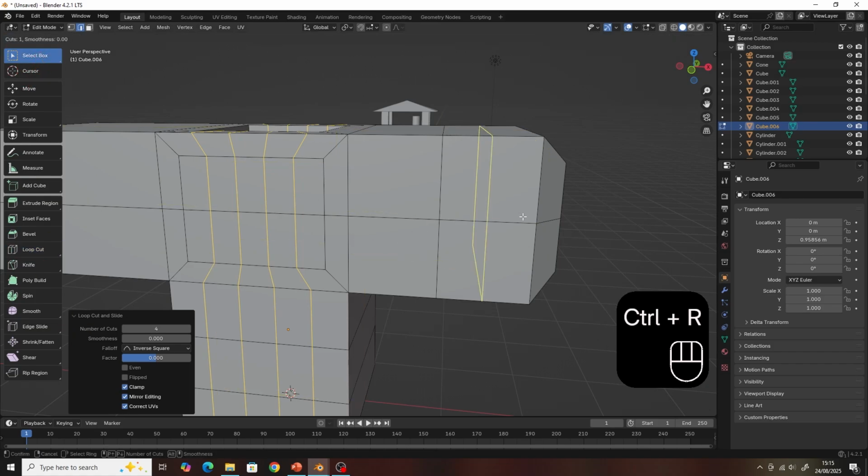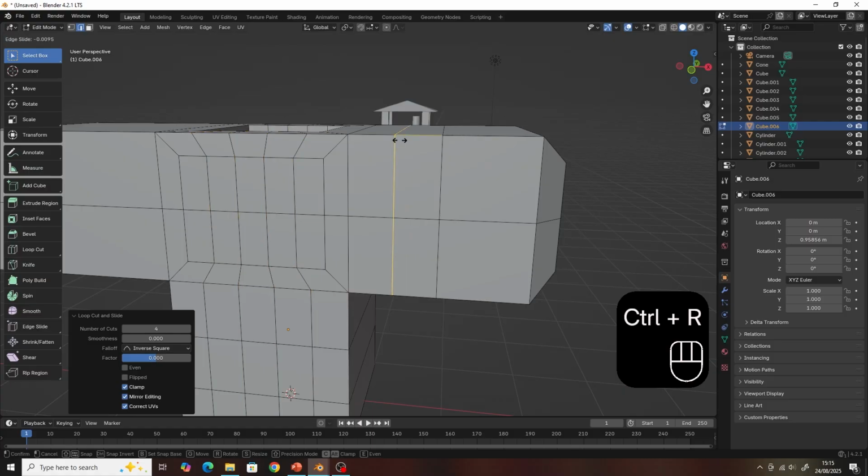When you use the shortcut version, you'll have multiple stages where you can press left click and it'll say, okay, let's move it between these polygons. Is there any specific location where you want to put it? If you want it just in the center, just right click. So it's left click, right click, then move on as well.